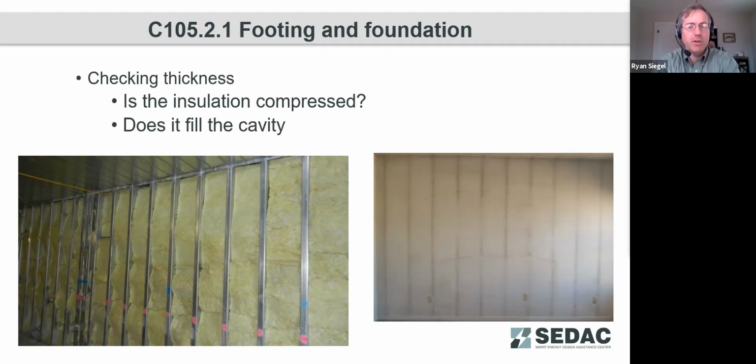And so you may have the warm moist air on the interior, and that moisture is attracted and potentially condensing onto that wall, and allows dirt and dust to adhere to that wall. This is typically due to not having any continuous insulation or a non-thermally broken wall assembly.